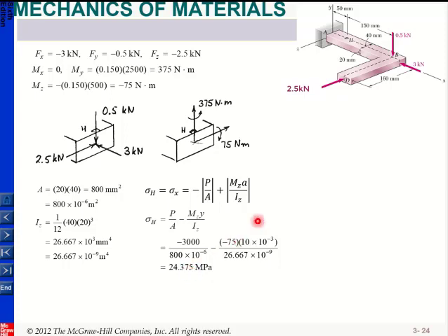Okay. And then for shear, I told you that Vy does not create any shear. The only shear stress created will be according to Vz. And since this is rectangular, don't forget that for a rectangular cross section, if you are looking at the maximum shear stress, which happens on this line where H is, at the midplane, I can use this formula.